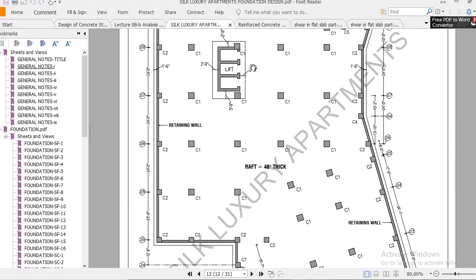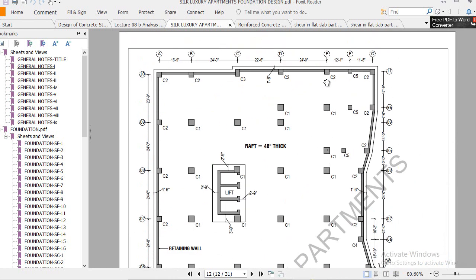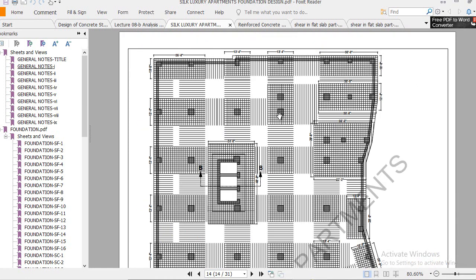You see here there is enormous shear loading on these interior columns, enormous axial force coming to these columns, because it is around about a 13-story plaza. So there is a very heavy loading over these interior columns when you are going to design the footing for such columns, and punching shear will govern.